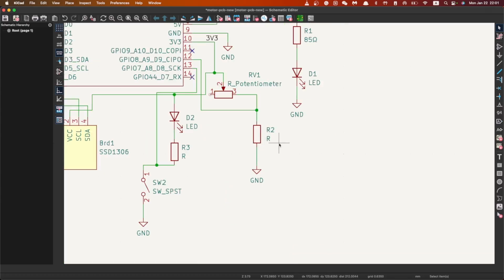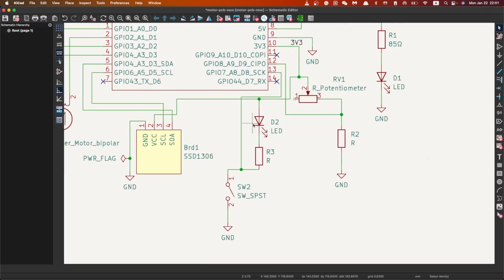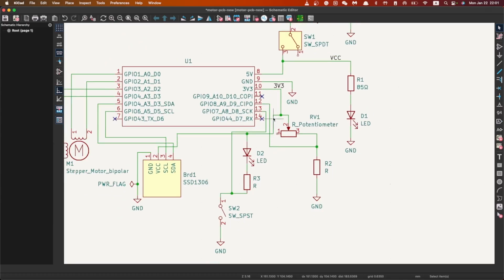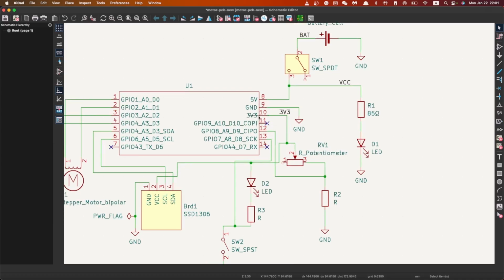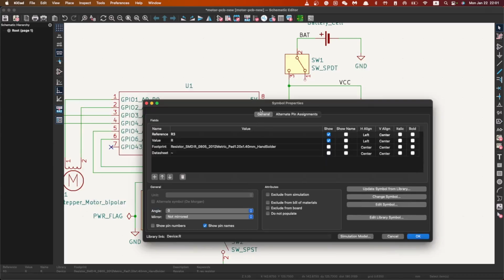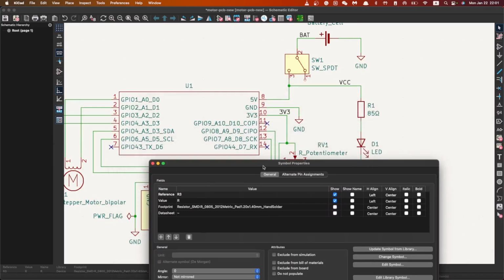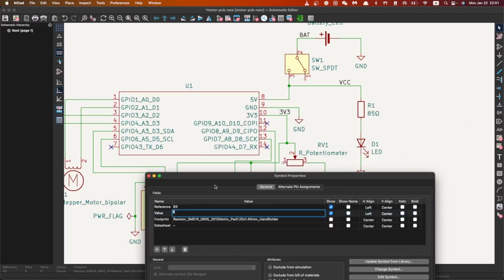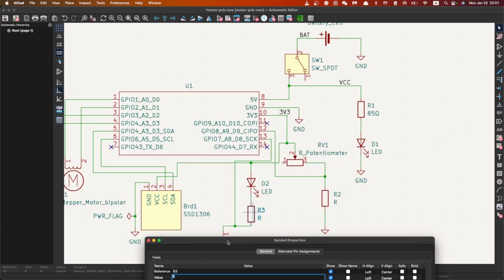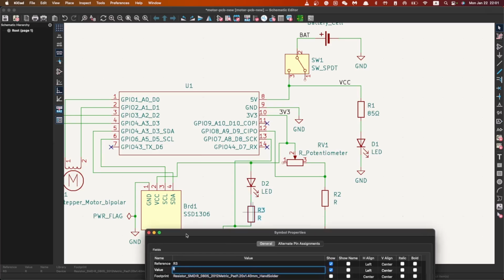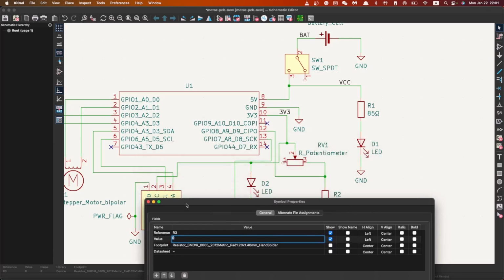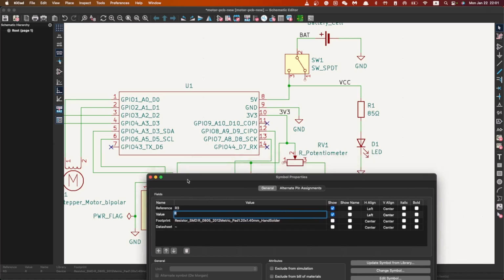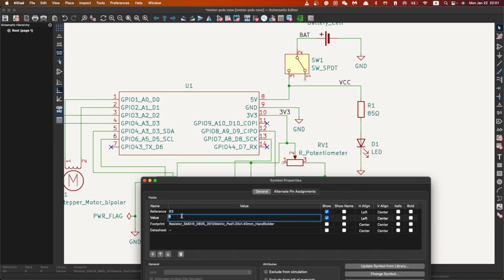It is the same for this D2 and R3 series circuit, but the only difference is that the output voltage here is a regulated 3.3 volts power supply from the MCU. So we can do the same calculation as well, because we are using the same LED for both D1 and D2. Their electrical characteristics shall be the same, so their correlations between forward current and forward voltage are also the same.